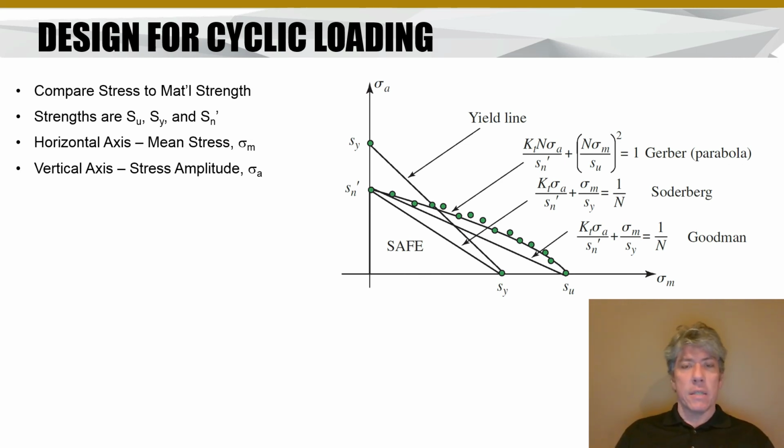In that case, we could consider either the yield strength or the ultimate strength of the material. Probably yield, because we don't really want our parts to deform plastically, so we'd like to keep the material stress below the yield limit. So on the horizontal axis, the yield stress would be a natural point to consider as a limit. Everything to the left of that would be okay.